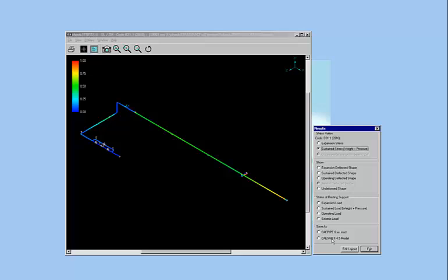And there are more advanced features, but we will reserve that for another video. So here's a summary of what we just did. We took a single line from AutoCAD Plant 3D as a PCF file, ran it through checkSTRESS, and looked for basic code compliance issues by studying the stress ratios. And what do we mean by studying? I simply mean, is it red or blue? If it's red, then there's cause for concern. If it's not red, it's okay. It will pass code compliance.